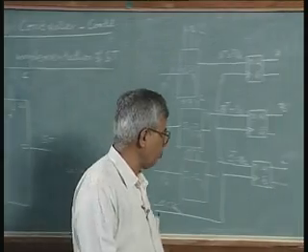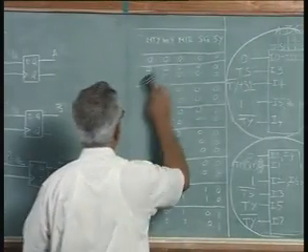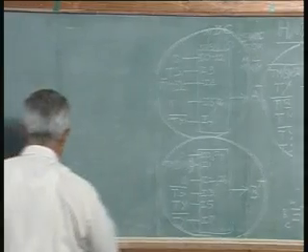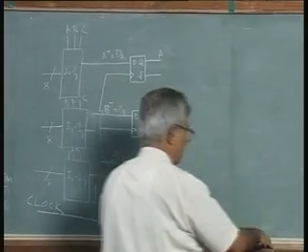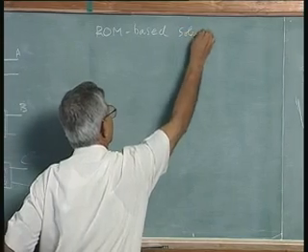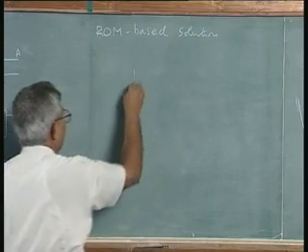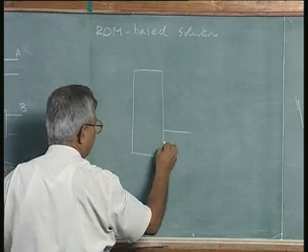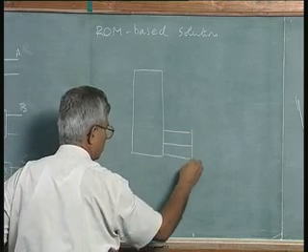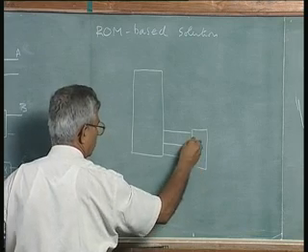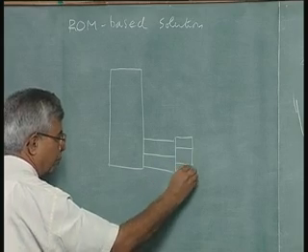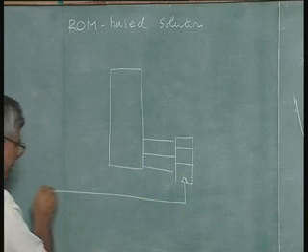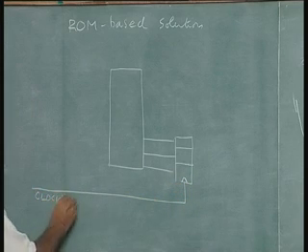Of course, you may want to have a ROM based solution for this. Yes, it is possible. What will be the size of the ROM that will be required? We have 8 states. Suppose you have a ROM based solution. What do you mean by ROM based solution? The ROM keeps everything and drives the flip flops. Let us call these flip flops a 3 bit register, with a clock which is common to all the 3.